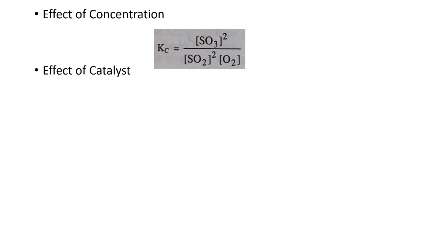Thus, the gaseous mixture which enters the chamber has an approximate composition of 8% SO2 and 10% O2. It requires a larger amount of oxygen, and the rest is nitrogen gas, that all of you know.